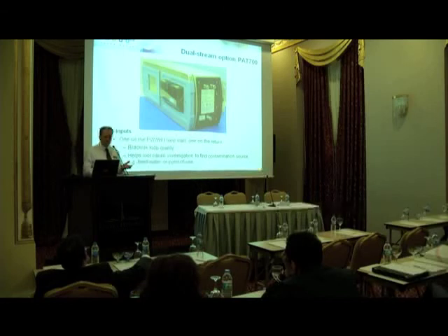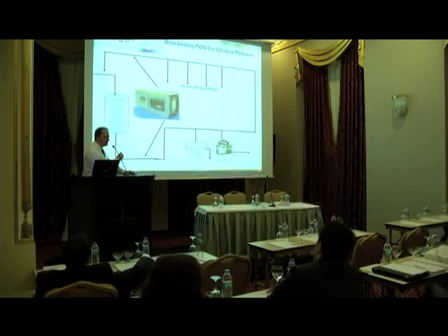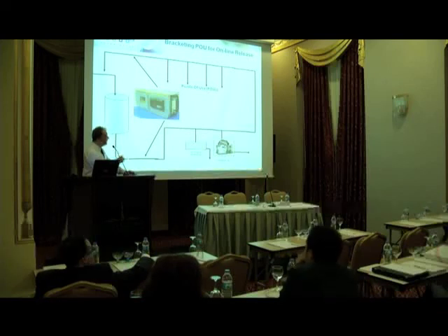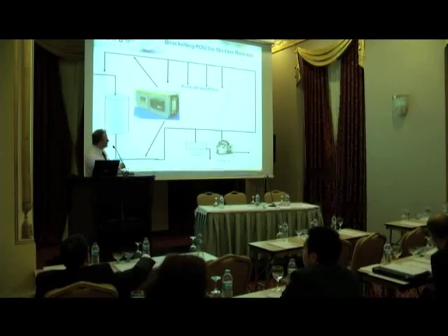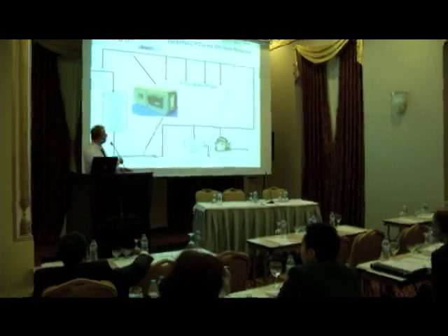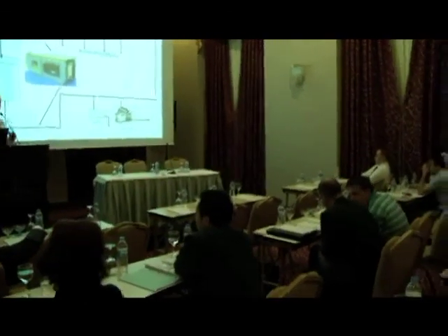So typically, what I've seen people doing is putting the TOC analyzer at the end of the loop. The argument is that the water quality then, any excursions will be captured by this. However, you have to then ask yourself the question, where did the excursion come from? If it came from the feed water here, if we monitored at this point, we'd know where it was coming from. If we measure here, it could be one of the points of use is taking a sample back into the